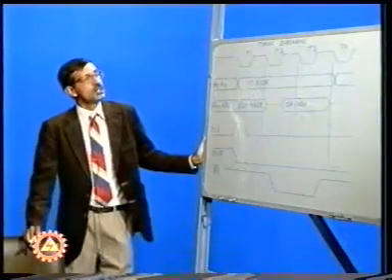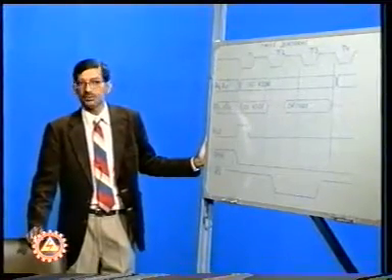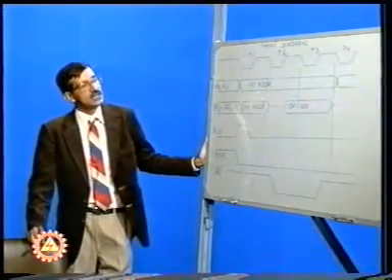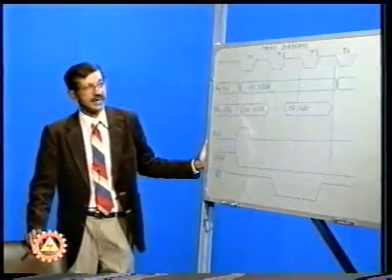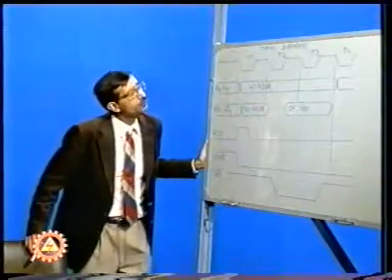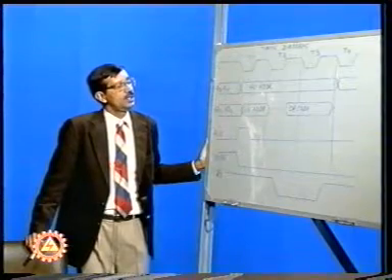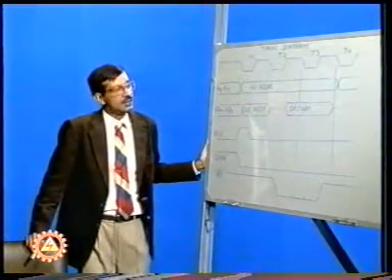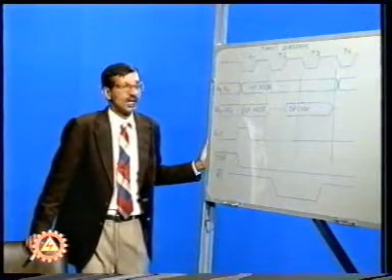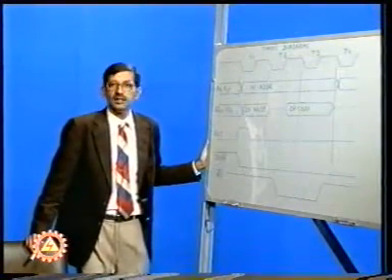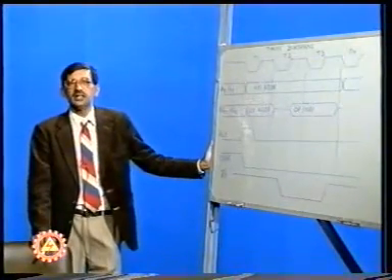There are certain cases in which the opcode fetch work would be over after the first 4 T states. In certain instructions, we might still require 2 more T states for carrying out the further action. During the fourth T state, that is T4, the instruction code, that is the opcode which has been fetched, is decoded and machine cycles are encoded if required, and the information is passed on to the timing and control block, which carries out the further action.